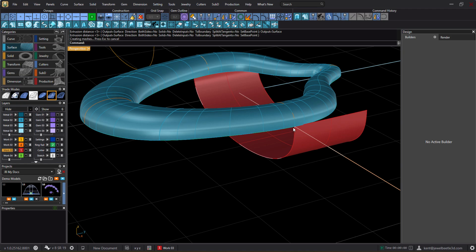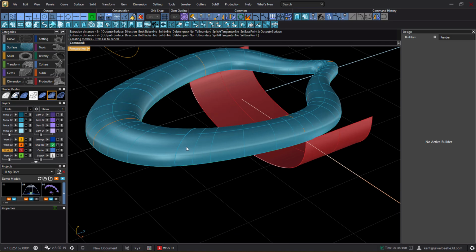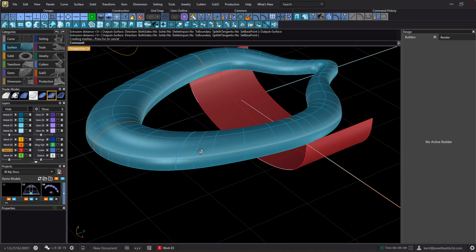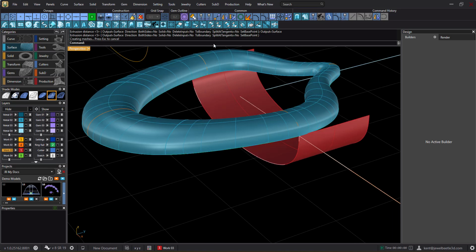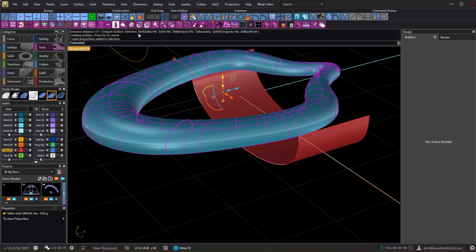All right, so we're going to blend now, blend surf, and we want to blend this section around here to here. Now, we need a split here because this surface edge is going to keep going here. It looks like there's a natural split here. You can see this heavier ISO curve. You can see one over here too. It's just the way it worked out. So let's go ahead and select this and go to Tools, and let's say Split Edge.